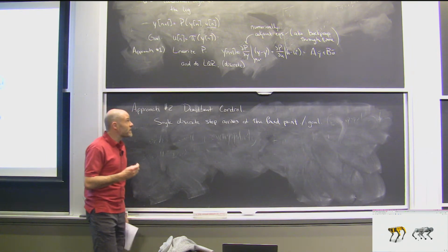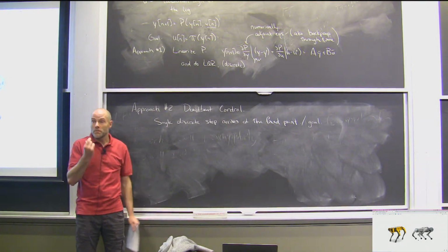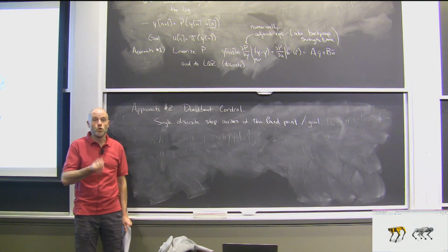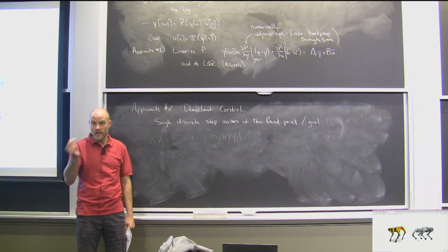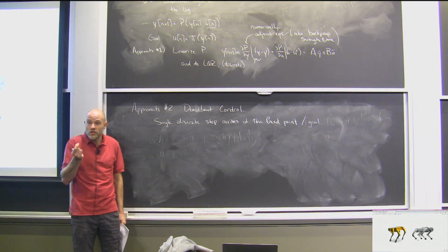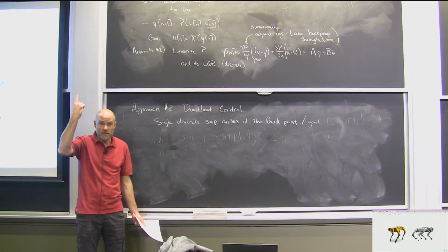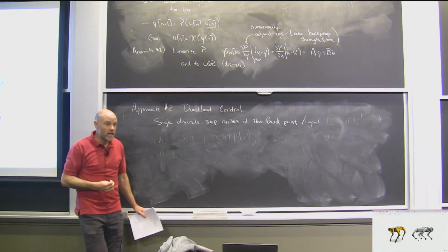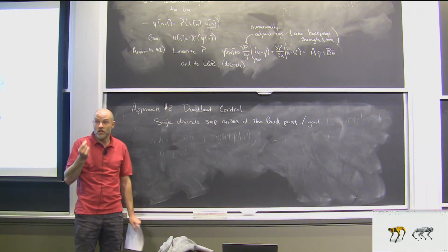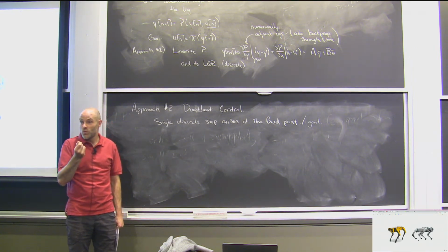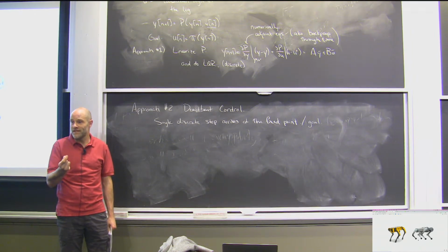So if I think about, in fact, the limit of the LQR problem, where I remove the cost on control actions, then in continuous time, that would be bad. That would turn my gains up to infinity, right? In discrete time, you can actually just arrive at the goal with finite cost in a fixed amount of time.